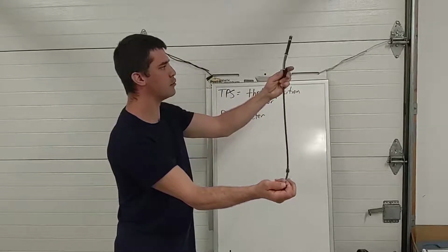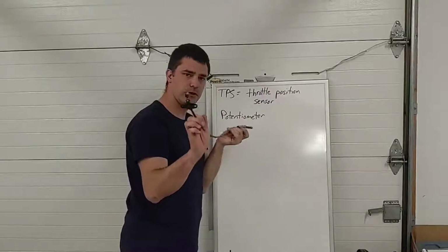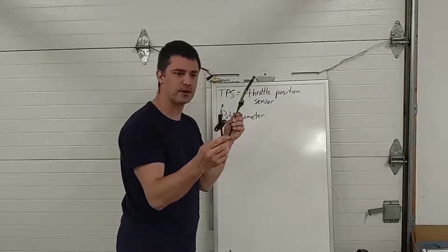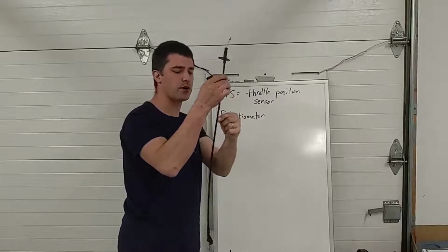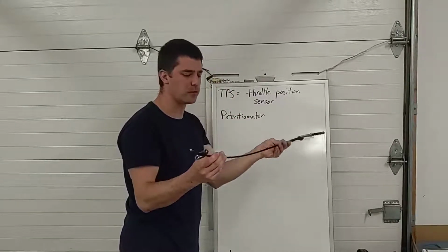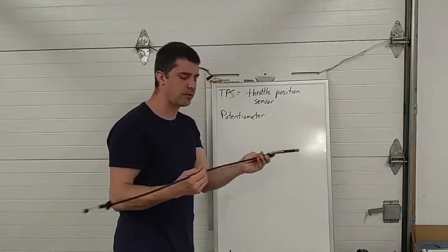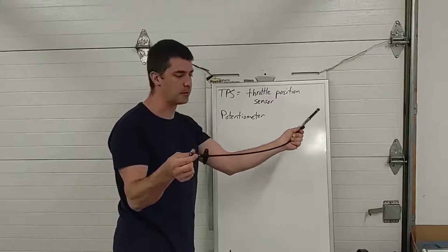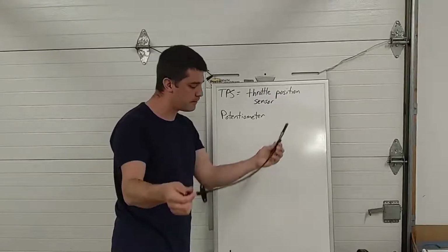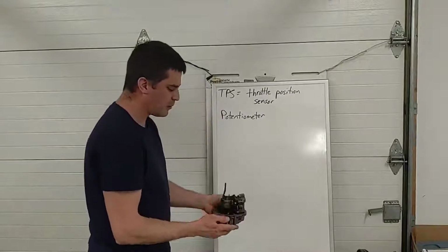You can see how that cable moves. Okay, so nice simple system. It's mechanical. Of course, you know what's going to happen to this cable. This is no different than a bicycle brake cable, only maybe a little less well made. Of course, over time it's going to wear in there. There's going to be some play or some slop, so you're going to get a little bit of a lag when you hit the throttle. Okay, but enough of the cable for now.